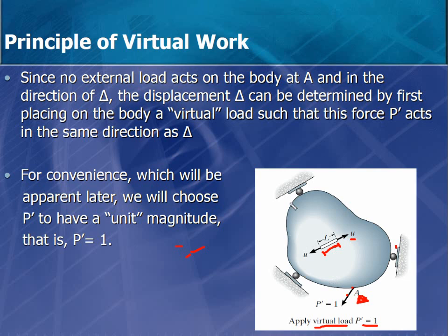Then if I assume that the loads are not there, there is 1 unit load and the direction is the same direction that I want to find delta, due to the energy methods procedure, that the load must be in the direction of the delta or the deflection in order to calculate work there, then this load is going to create internal forces within the body acting on the length, on the elements that we used the first time.